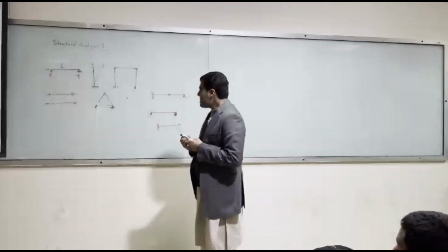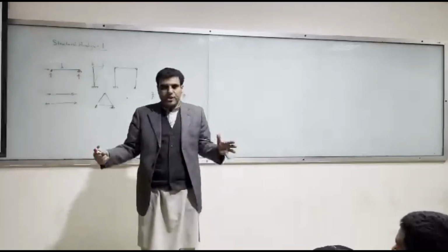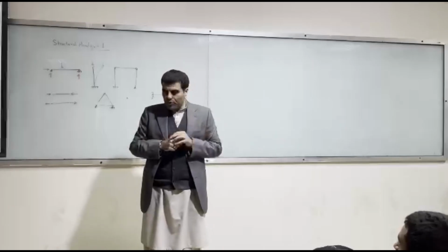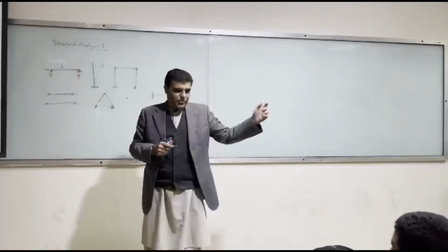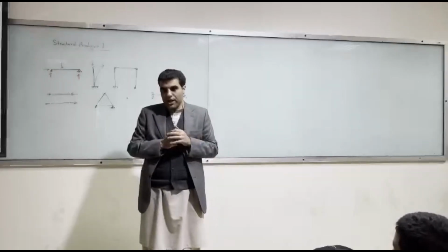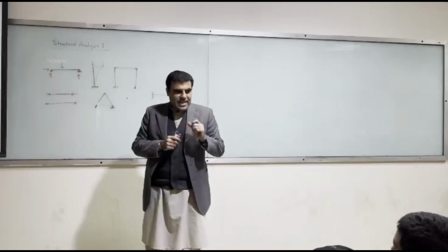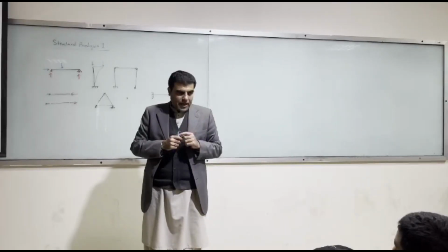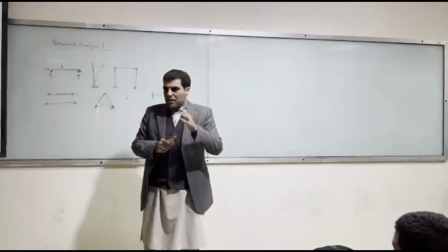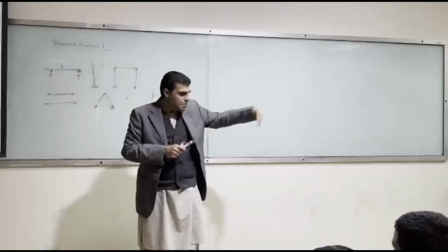The basic theme of superposition is that if you have a structure which is subjected to different loads, for example point loads, say 10, 20, 30 point loads, then the displacement at any point is equal to the sum of the displacements of the same structure subjected to each and every load independently.